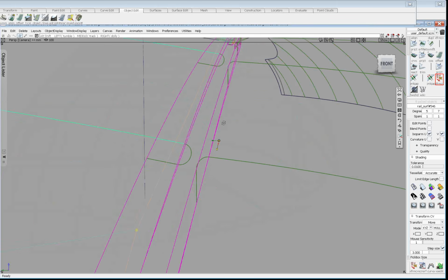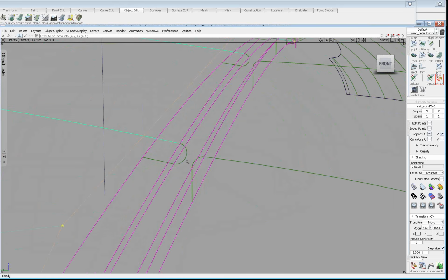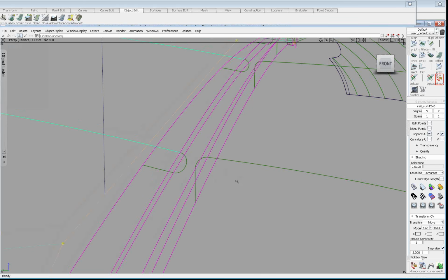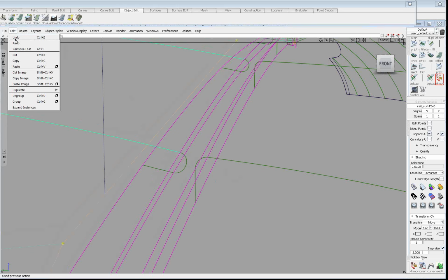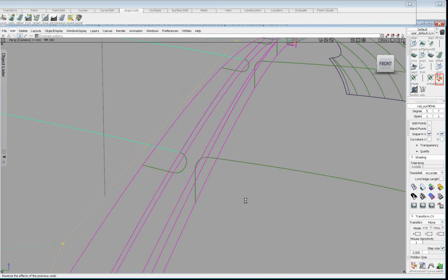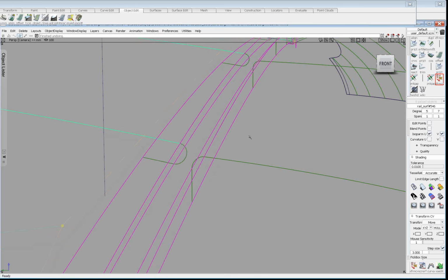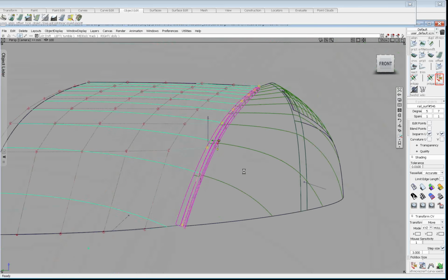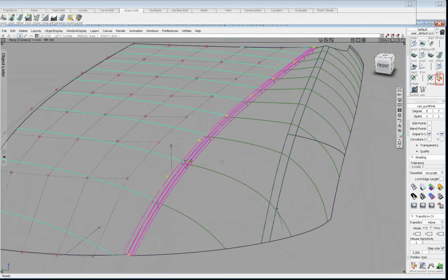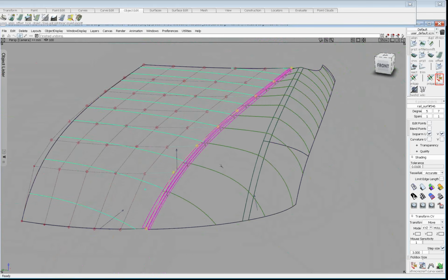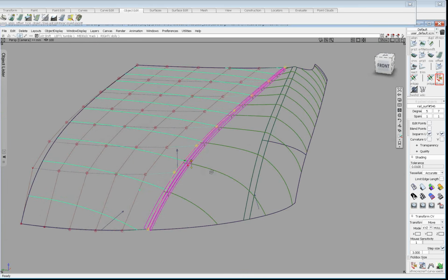Now you'll see that I've moved the hood, still maintaining a 2 millimeter gap, or a 3 millimeter gap, in between there. Let's just do an undo here so you can see the previous condition. 3 millimeter gap, sorry. And then let's redo it. So putting the panel gaps in position means you can continue your design process, and yet you still put in a fairly sophisticated set of surfaces that maintain a gap condition between them.